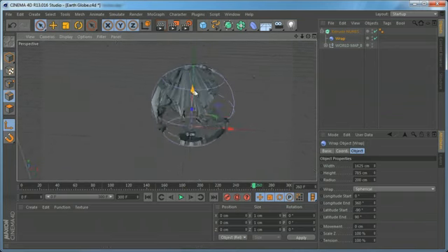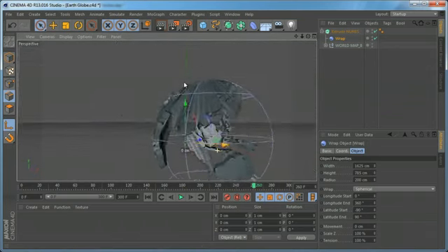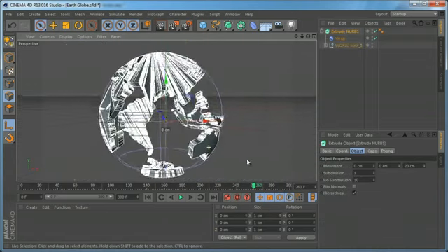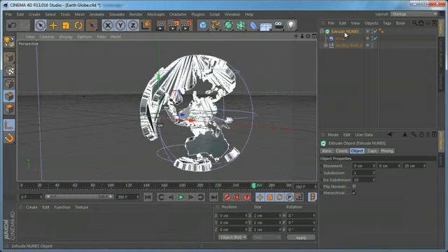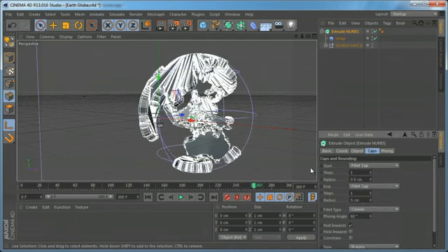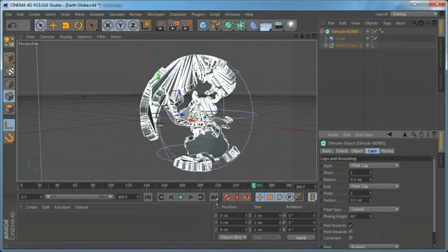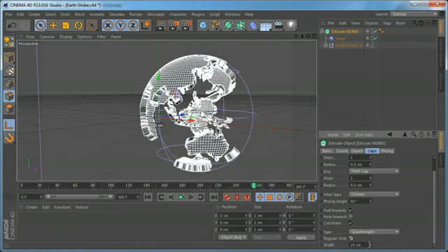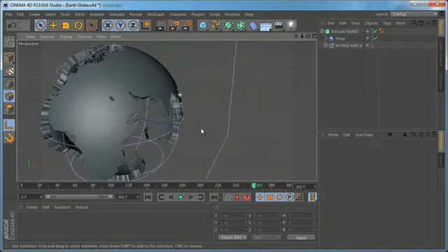And as you can see, the Earth doesn't look good, and that's because we actually don't have any geometry to deform. So we need to come to the extrude NURBS, go to the caps tab, and set the caps to fillet cap and set the radius to 0.5 or 0.2, a very low radius. Click constrain and then choose quadrangles and click the regular grid, and now as you can see, it starts to look better.